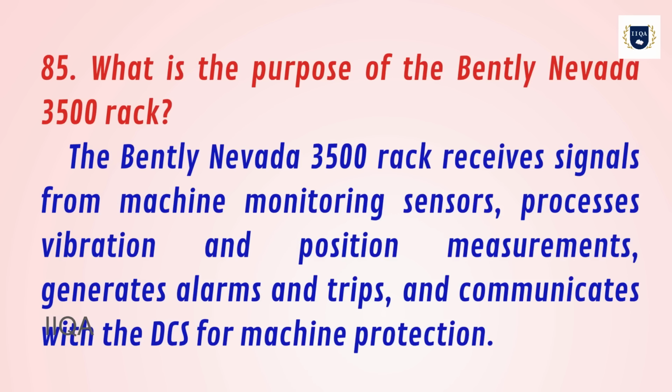85. What is the purpose of the Bentley Nevada 3500 rack? The Bentley Nevada 3500 rack receives signals from machine monitoring sensors, processes vibration and position measurements, generates alarms and trips, and communicates with the DCS for machine protection.